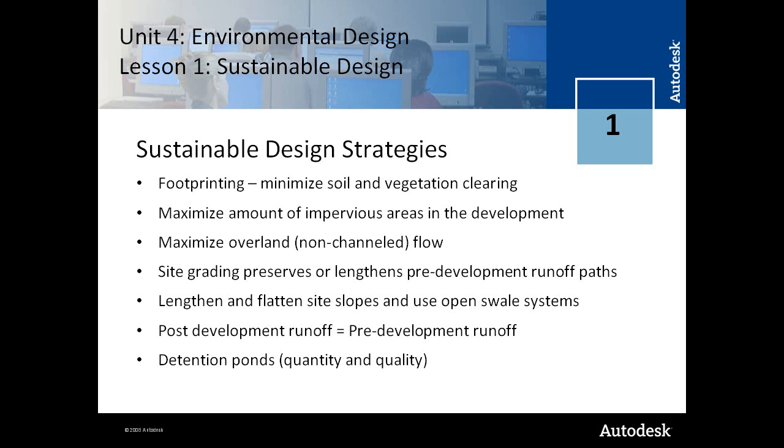You want to maximize overland flow, essentially minimize the use of channels to manage flow and discharge from a site. Ensure that your site grading plans either preserve or lengthen the pre-development runoff paths. And once again, this is controlling the overall discharge of stormwater from your site.